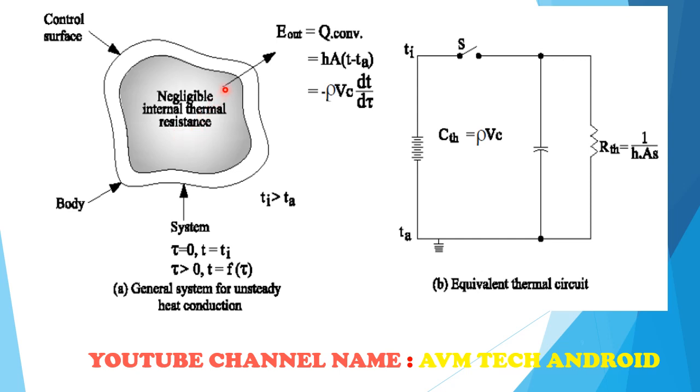So the energy which is leaving, that is heat that is dissipating, is mainly governed by convection heat transfer, that is hA delta T. And what you can also observe here is this is a body, this is a control surface, this is our system, where when time is 0, the temperature is equal to the initial temperature.